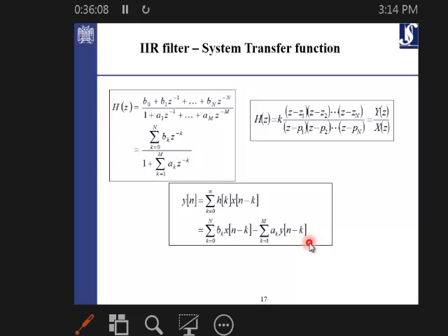Depends. Isn't it always good if I have some error and I don't give feedback, I just keep pushing this error over and over and over. That's why when we go further in the theory of DSP, other areas, we use the adaptive filters. They are FIR filters, but they are actually using least square error estimation. So they get the error submitted to a system, and they start to calculate the least square error using gradient descent algorithms or Newton algorithms. They try to minimize the error based on the cost function, and still they use the FIR filters.